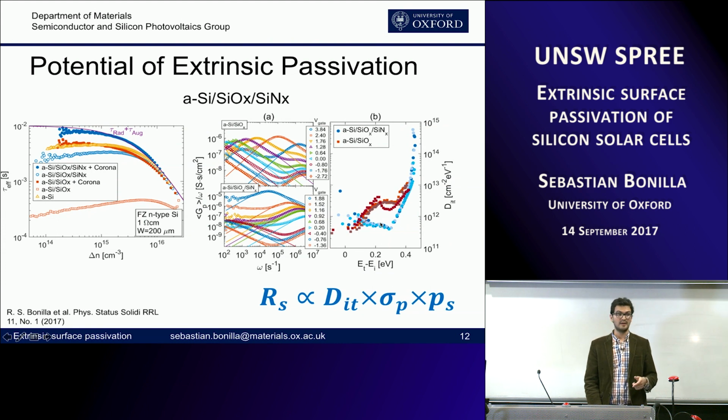So if that is the case, then the only thing that can explain why you have such low recombination velocity, which gives you extremely high effective lifetimes, is the fact that the capture cross-section for those states has to be really very small. So this is something that maybe before wasn't so important or so taken into account, and here we see that it's actually a key factor.